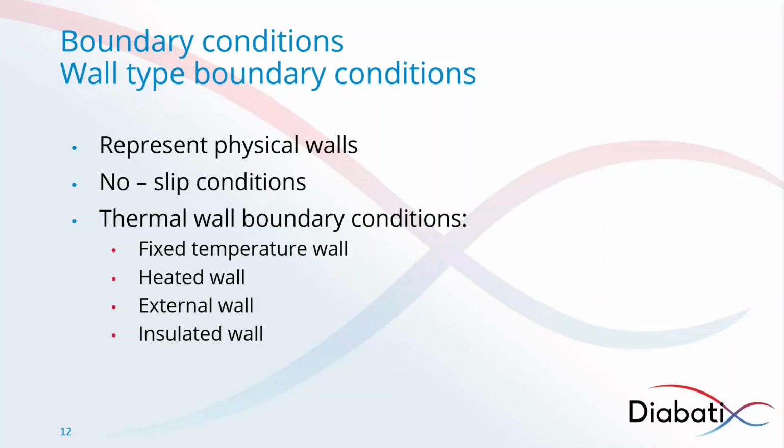So the fluid will have zero velocity relative to the boundary. The normal velocity component is set to be zero. A boundary layer will develop in a no-slip boundary condition. And to use one of the terms from before, this kind of boundary condition is a Dirichlet type boundary condition.